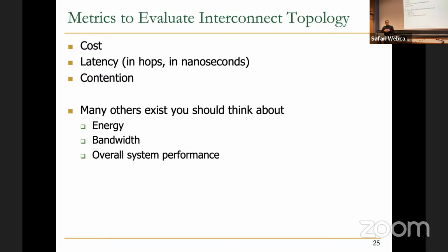But the moment you want to see the performance of the system, so you run your GPU application, your network is beautiful because now the latency is 150, but the overall performance in your GPU application would be something around 1% or maybe less than 1%. Because essentially that 50 cycles is possible to tolerate using the latency tolerability that you have inside your GPU.